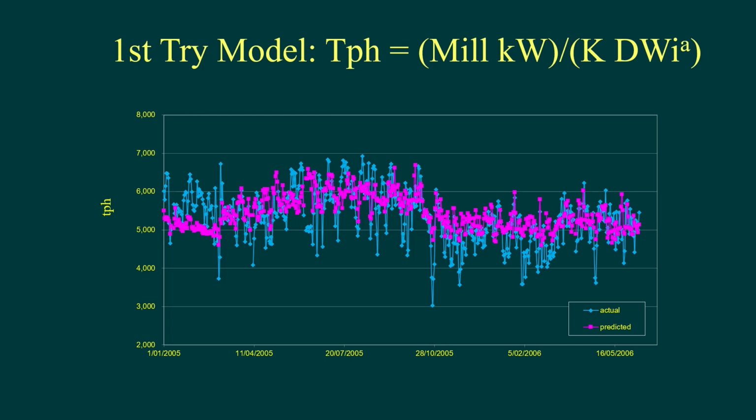So you look for a time when the mine plan has had a big shift from one of those ore types to the other. We know when that shift is made in the mine, and then we simply look at how many days, or even hours, later our mill starts to respond. That is some indication of the lag between what happens in the mine, specifically when there is an ore change, and when that response comes through to the plant.